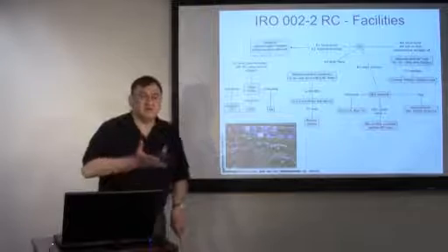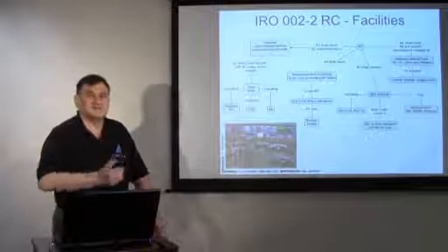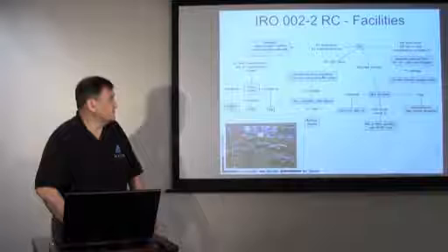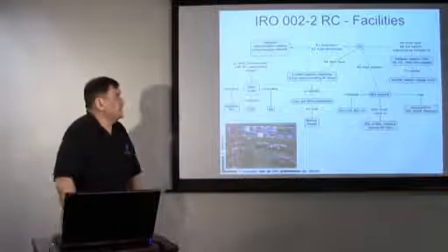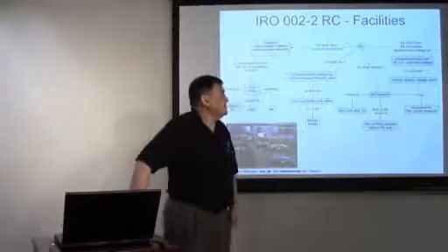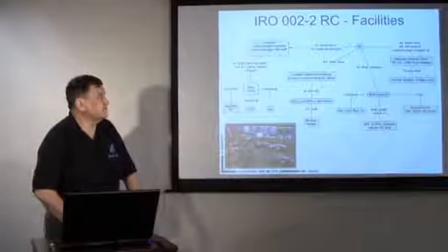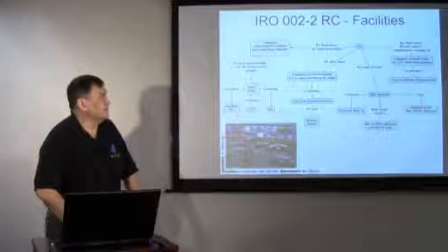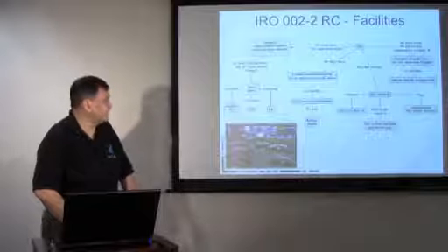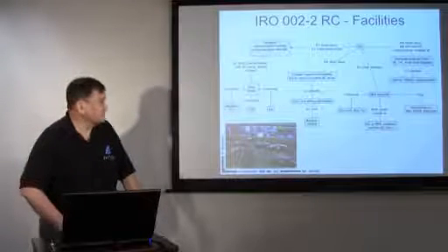So this is saying, really, the reliability coordinator has to have operating models. It has to run these applications in real time. It says they will control the maintenance outages. When those outages are taken out for service, then they have to make sure that it's either at a non-critical time or they have a backup for that. So it's saying that these tools have to be a critical function.